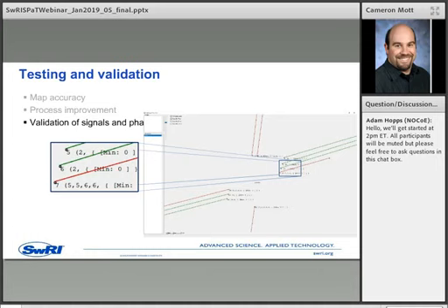In addition, one of the highlights from our project is our ability to forward messages from the field back to our lab. It allows us to monitor and verify some of those SPaT and MAP messages in real time from each of the signal controllers. This is a representation of the phase and time remaining for each of the phases based on the reports from the signal controllers. As you can note, there are still some improvements that are needed from the signal controllers.